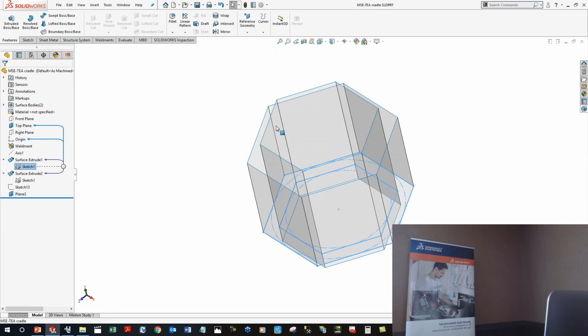What the structure system gives you the ability to do is instead of drawing lines, you can apply a weldment body on any edge of a plane, edge of a surface, line, between 2 points, between reference planes that intersect, and it'll treat it as a sketch, and it'll put a body on there. Let me show you how that works.